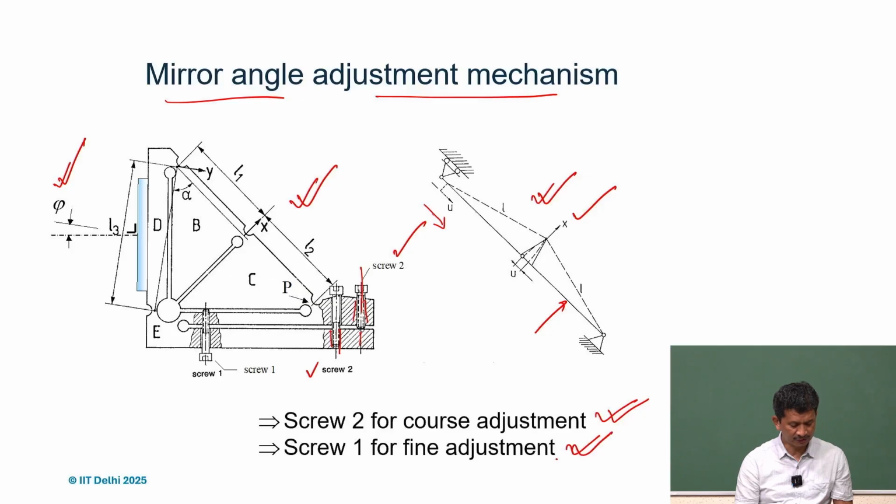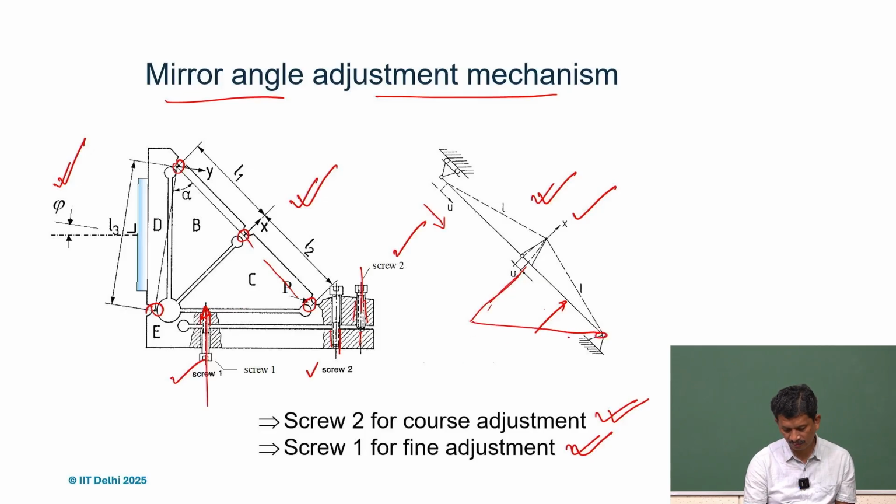What you also realize is that screw 1 here is threaded here, and as you tighten, you are pushing this block. As you push, you can see hinges here. Once you push it here, actually you are moving this link. You have a hinge here, you have another hinge, and you are simply pushing it here.